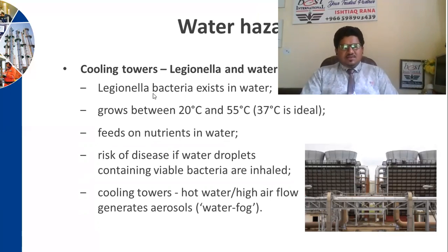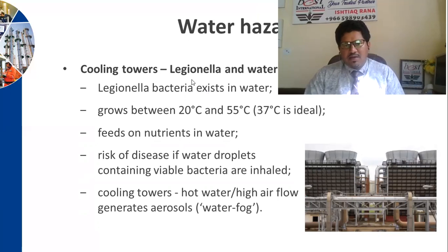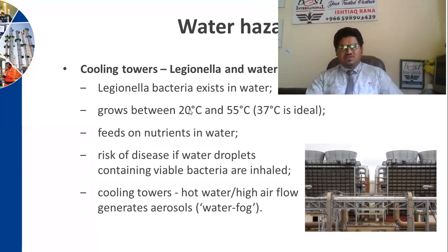A few more water hazards, like cooling towers. We could get Legionella, or the water fog. This bacteria exists in water and also grows between 20 to 55 degrees, with 37 being ideal. It feeds on nutritional water. There is a risk of disease from water droplets containing viable bacteria from cooling towers.